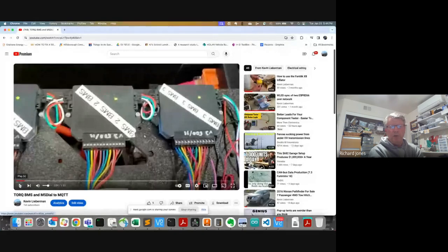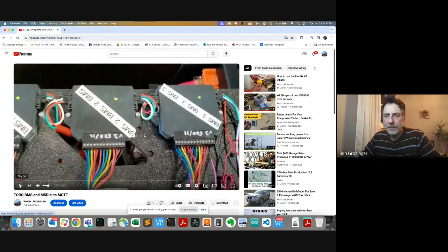Yeah, I've worked with many different BMSs, and ultimately, you've got your array of voltages that, like Kevin is showing on his display, whether it comes from a Ziva or an Orion or a dilithium or any number of other BMSs in your vehicle. Somewhere you need to know what those voltages are, and something needs to make a decision to turn the charger off if they're getting too high, or slow the power down to the motor controller if it's getting too low. Those kinds of decisions.